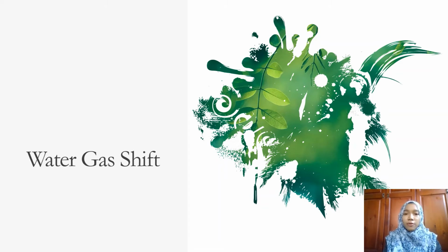So as presented before in the previous presentation on the SMR reaction, we know that the SMR reaction would produce the most amount of hydrogen in the production unit. It uses methane as the raw material and water supplied as steam to produce carbon monoxide and hydrogen. This is a good source of hydrogen, but it also releases carbon monoxide, which is very harmful to the environment. To counter this problem, another reactor is placed after the first reactor, which is the water gas shift reactor.